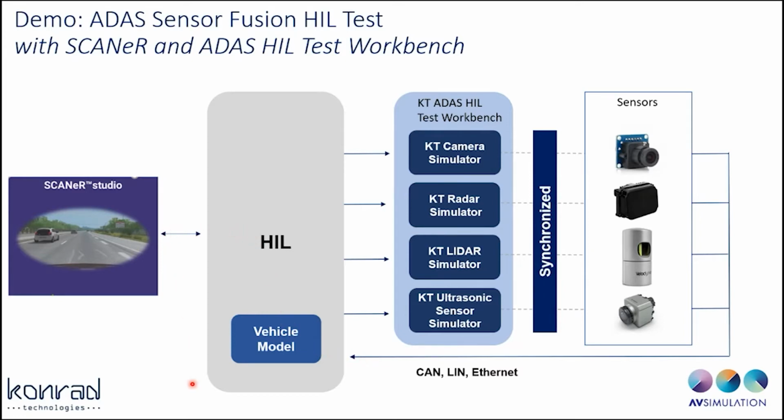So by doing this particular test method, there's a couple of key points that you're able to test. The first thing is you're able to verify, is the sensor working correctly? And that's what we would call module level testing. But then when you combine the sensor performance with the ECU model test, then you are now doing a subsystem level test to enable the right intelligence. And then if you connect that to the vehicle model test, now you're able to do system level test.